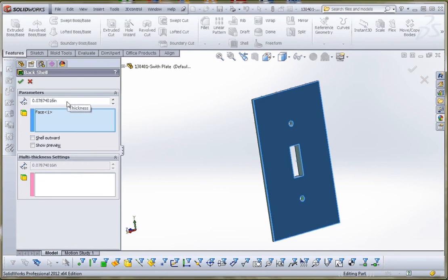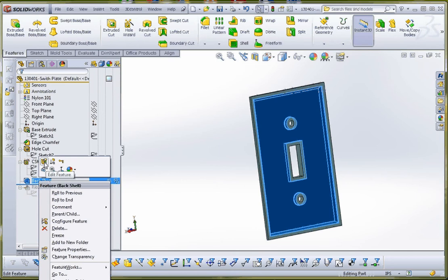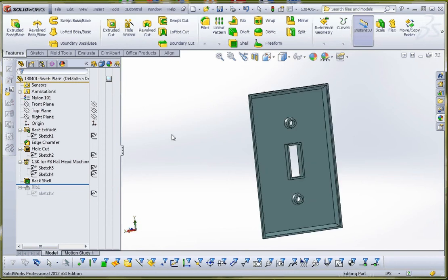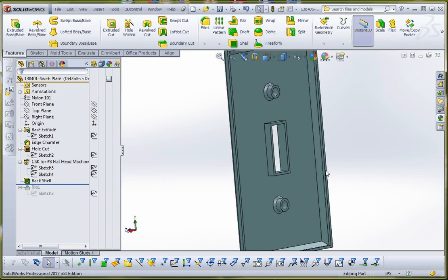So this element here, again, out to 8 significant inches probably isn't appropriate, but maybe 1/10 of an inch would probably be good. And that actually looks a little bit thick, so let's right-click on that and actually make that a little bit less, maybe 0.05 inches, and see what that looks like. That looks like it's in much better shape. So that's probably an appropriate thickness.